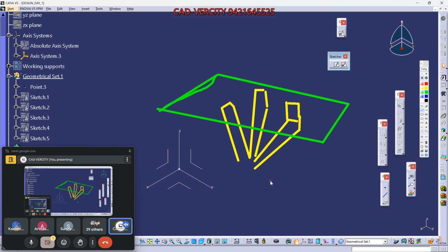Now, can you remove any one finger? Is it resting properly? No, sir. So, how many minimum points or minimum pads do we want to rest any part? Three. So, we call it the 3-2-1 principle. We need 3 points. Is the number 3 clear? Yes, sir. Simple. Then after that we will discuss 2 and 1.